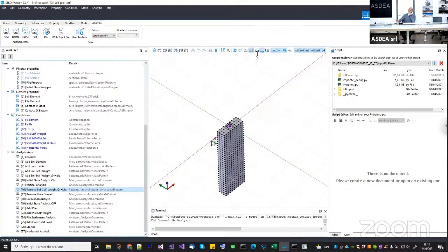Oh, okay. Yeah, it is fine, but probably you will have some problems also there because it will not go crazy as the previous contact element. But if you expect the gravity load to take a lot of iteration to converge and you want to reduce the time step, it's better to use the edge force or the volume force that we have in STKO rather than the volume force of the element, because in any case, whenever you do a nonlinear analysis, having the load applied all at once is not good, okay?